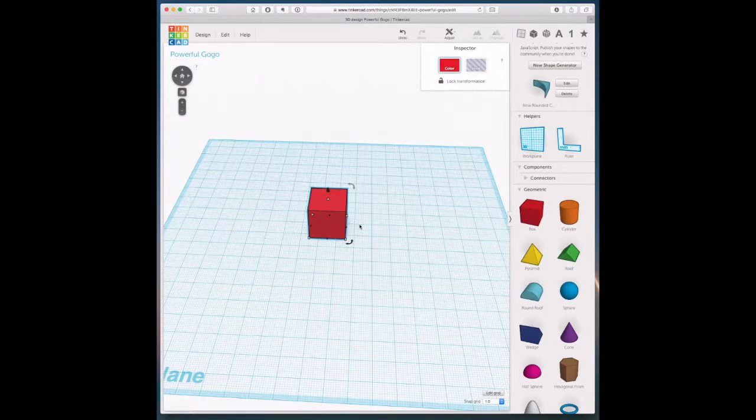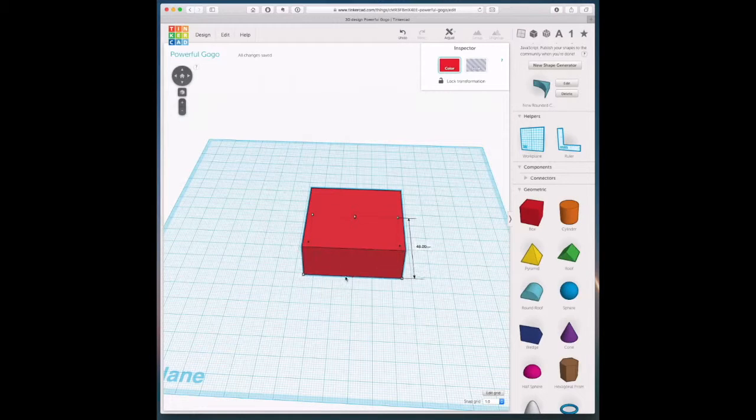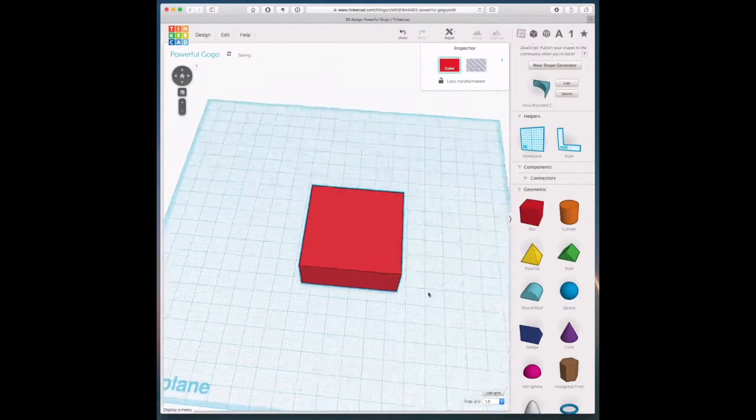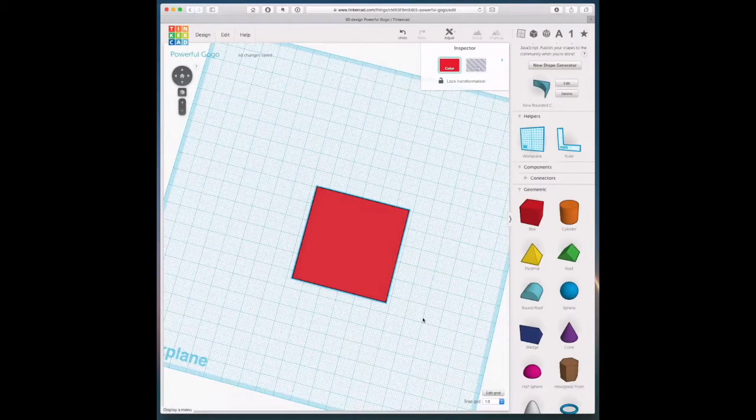Now, when you select a shape, you're able to manipulate it. You can change its size. Here we'll basically make it a little wider, and maybe we'll make it a little deeper as well. You can grab these handles like you would in 2-dimensional drawing programs, except now you're working with more handles because you've got more ways to manipulate the object, including growing its height.